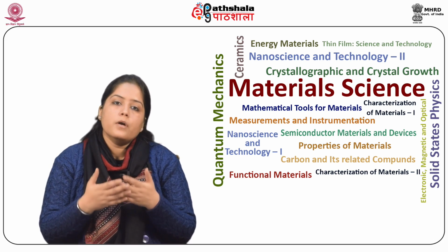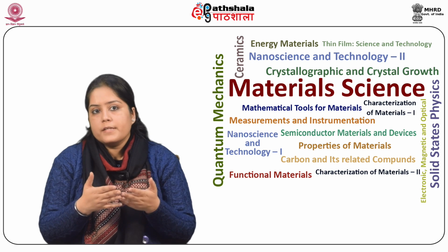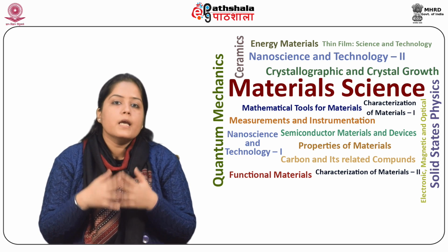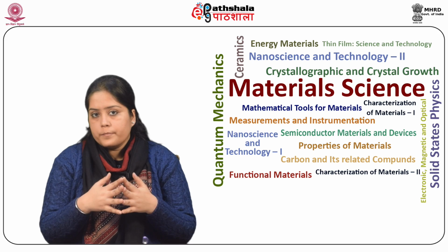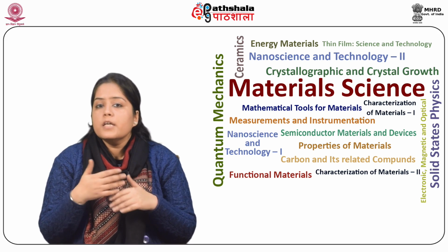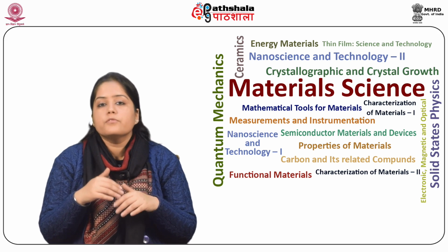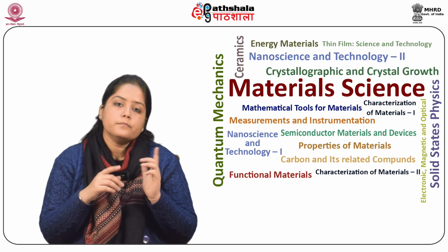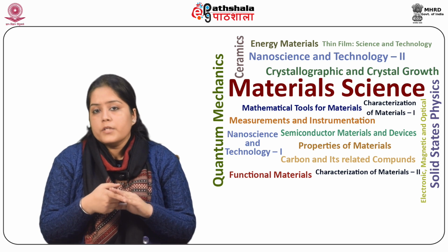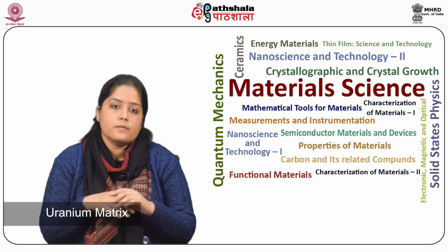Further, the uranium alloys based on fissium, UFS or UFZ, that is fissium, are being used in LMFBRs. Uranium fissium alloys are produced while reprocessing of spent fuels, in which an amount of the fission products like molybdenum, niobium, zirconium, rhodium, and ruthenium, etc., are left in the uranium matrix.